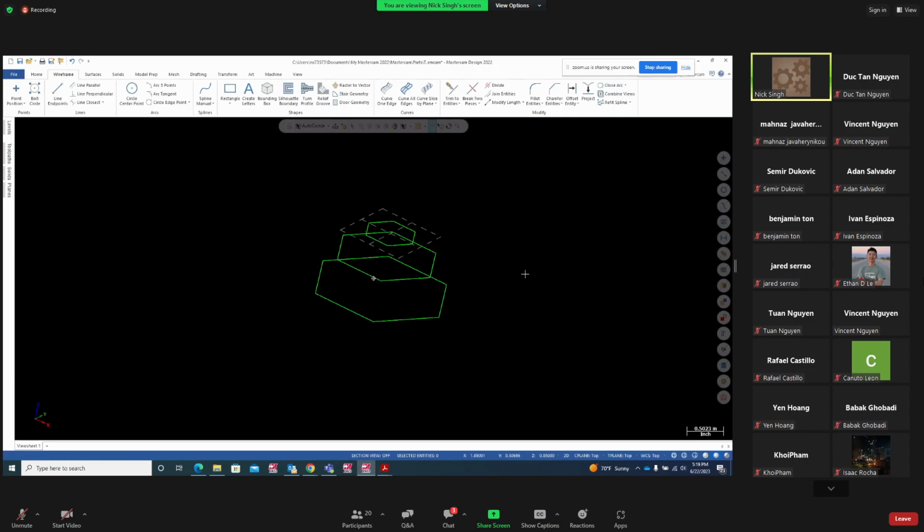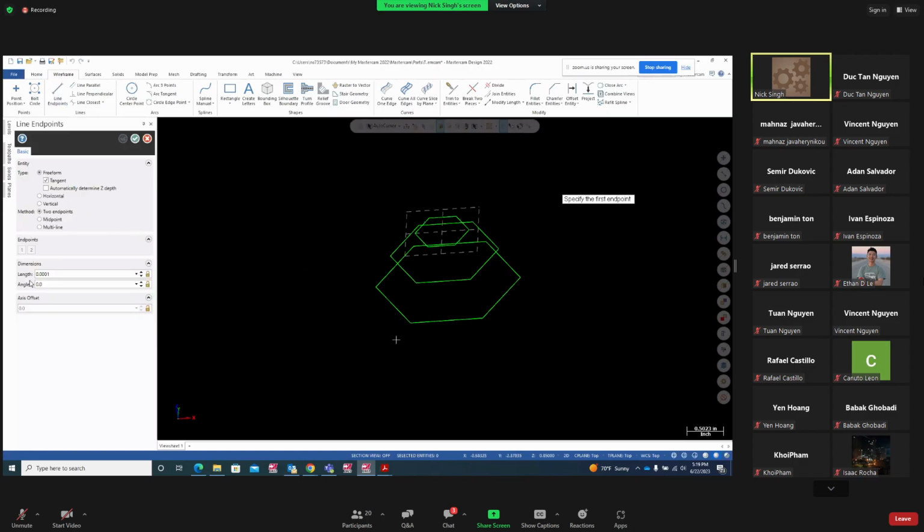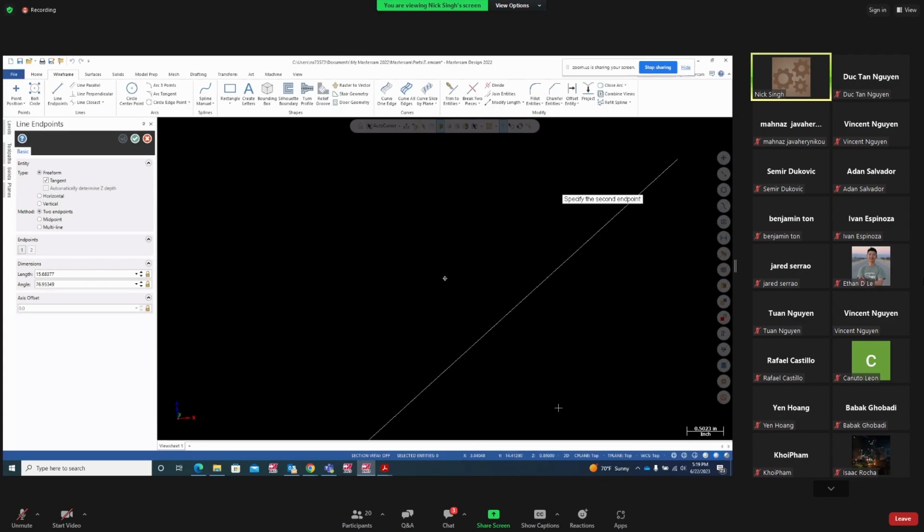Now we're going to create surfaces. Now to create surfaces, we have to join these lines. Now to join these lines, if you look at here, my Z is this one. If I'm going to start a line from here, I want to go to this one here. Look at this, my Z is controlling it. It starts as Z0.850 over here. Look at this, starts from 0.850.